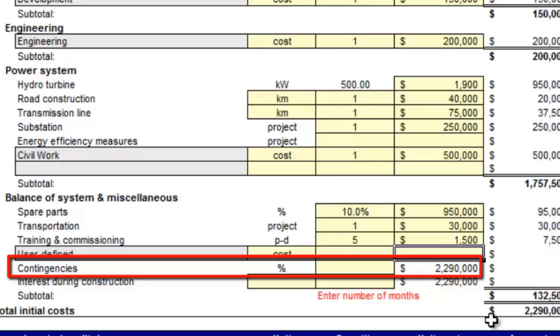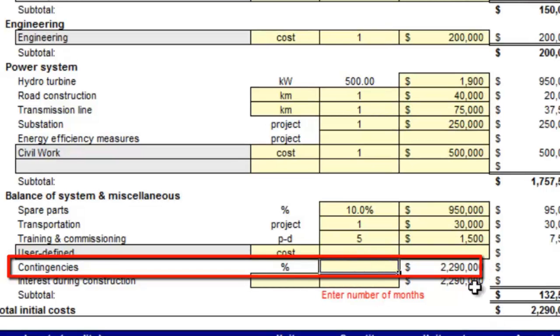Contingencies for hydro projects can be substantial, as there are many unknown factors that are usually only discovered on-site. For this project, however, we have a firm cost for generating equipment and a reasonable expectation as to what the expected dam repairs cost will be. However, adequate provision of funds to handle budget overruns should still be made, so we will use 25% as a contingency to offset such possible risks.